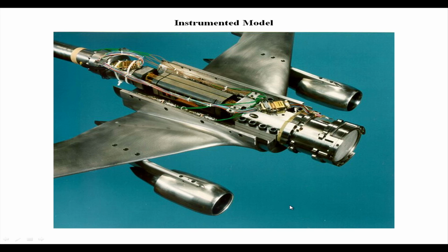Of course, it's not complete, in the sense that, as you can understand very well, some part of the fuselage of the aircraft over here is missing, but it has been opened up just so that we can appreciate that when we do the instrumentation it could be rather complicated, and we have to plan this layout so very well so that everything finds a proper place inside, and also we get the desired response from all the sensors that we have packed in there, and finally are able to extract data which can reflect the flow physics.